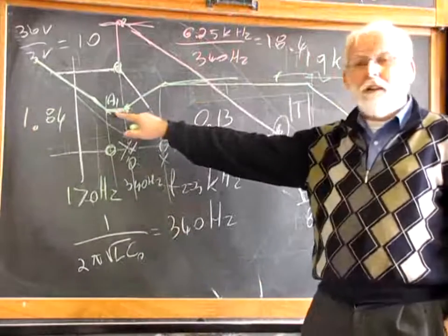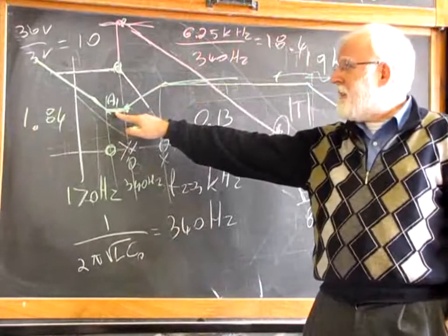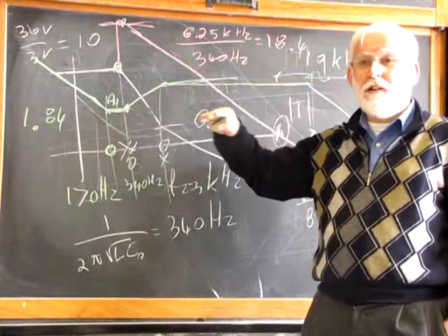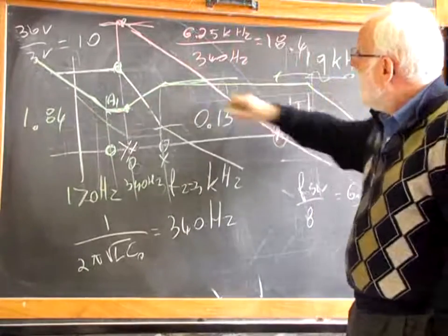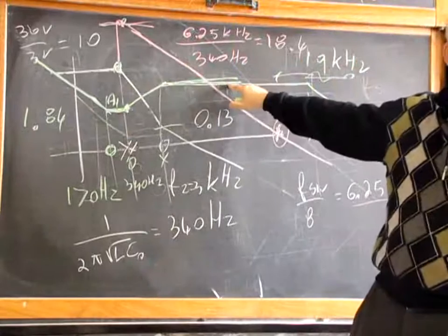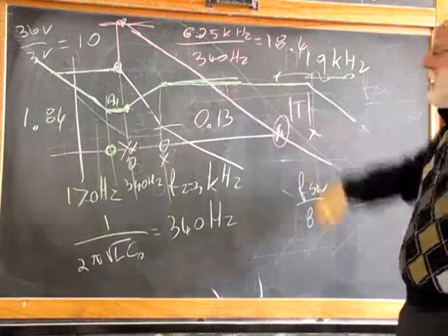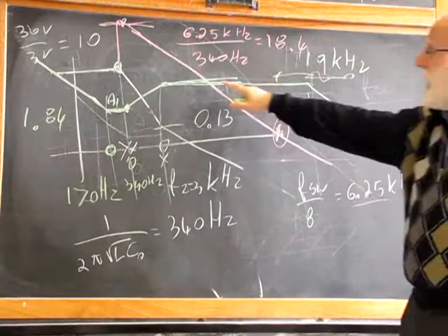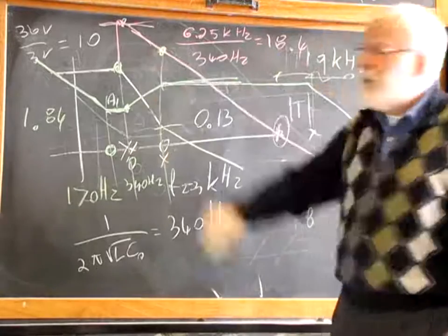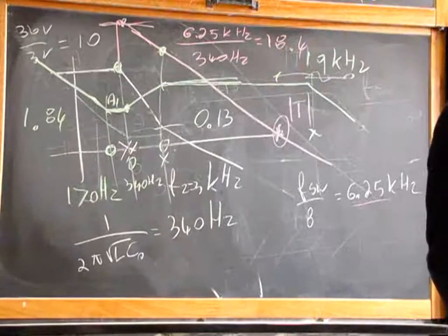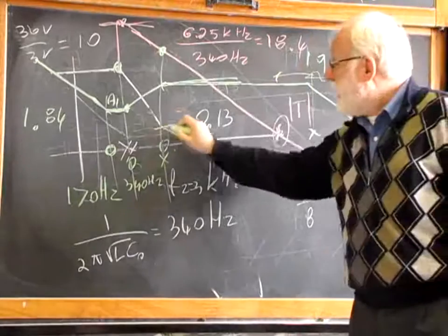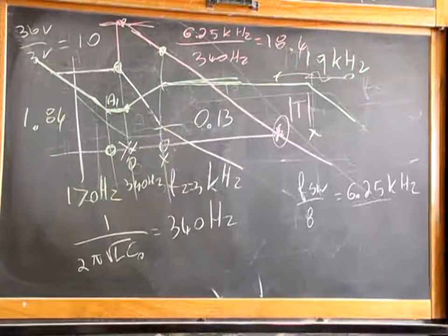And observe that in both converters, CCM, Bode's model, this first gain is quite low. And how much is this gain? We don't use it for design. We use it just for double check. This gain is equal to the gain I want, divided by the gain I get over here. How much is the gain I want?